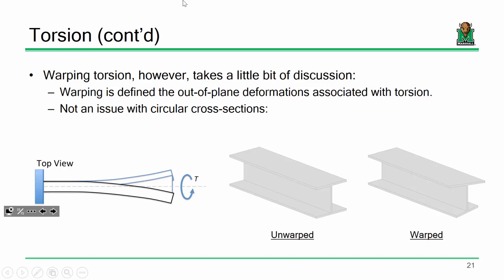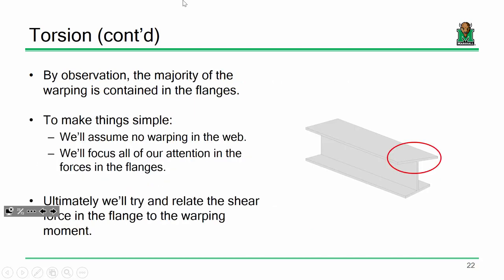That's why when you take an undergraduate course in deformable, you stick with circular sections. And if you're a mechanical engineer and you're designing for torsion, or you're trying to design some element to resist torsion, you're going to want to always use a circular cross-section anyways. So, food for thought. Okay.